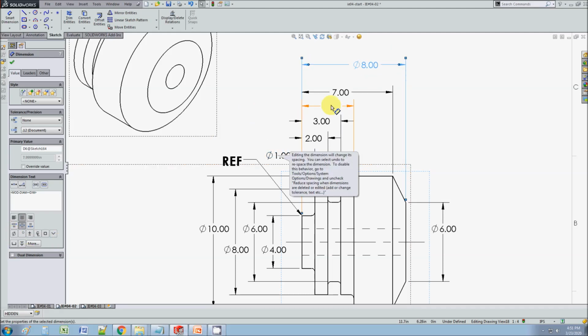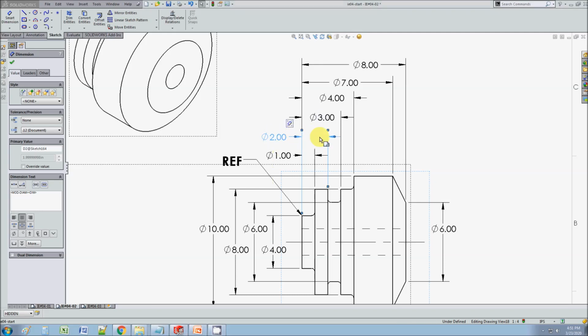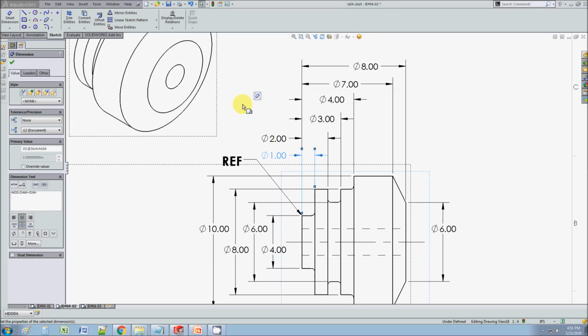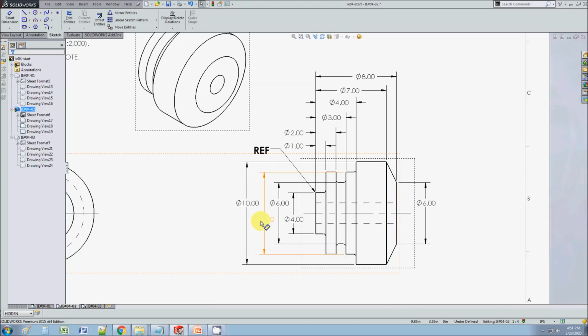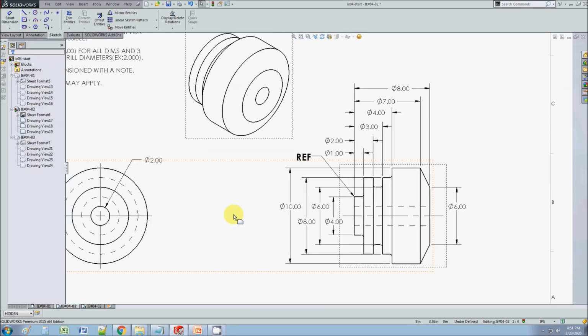You're trying to decide, all right, first of all, does it make sense? Second of all, can it be machined? Will the customer be able to use this easily? Okay, so here's the dimension here. See, this is what I did not like. I prefer that you do this instead, because you utilize the space a lot better in this fashion. Just like that. We have a hole here. So remember, we said holes need a leader. So I'm going to spell this as a leader, just like that.